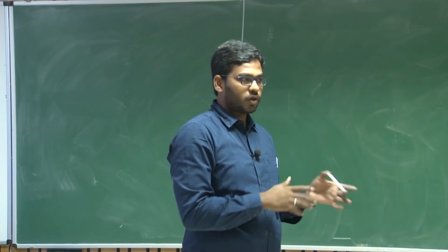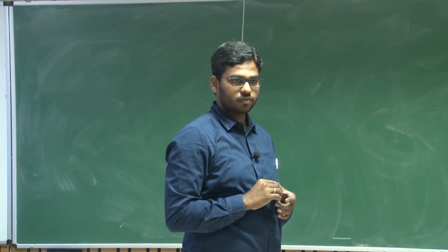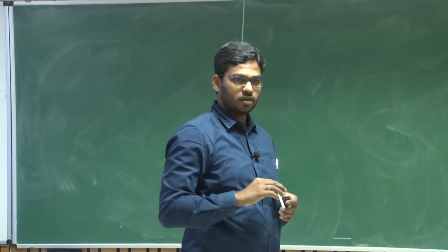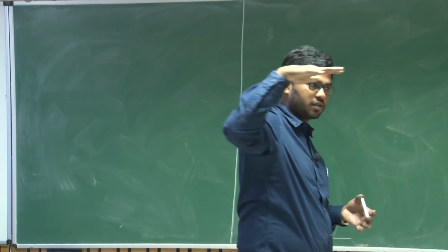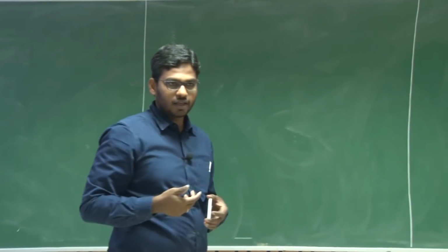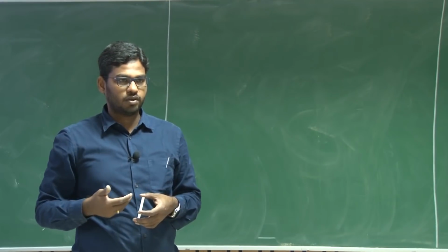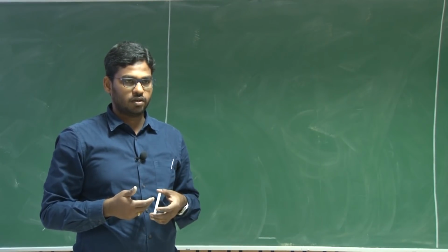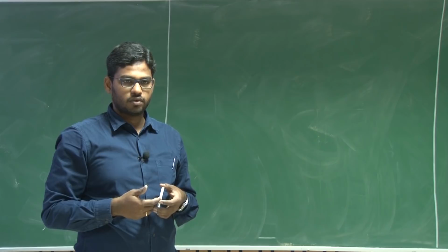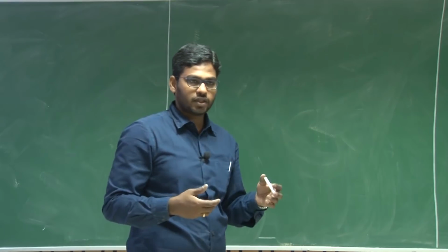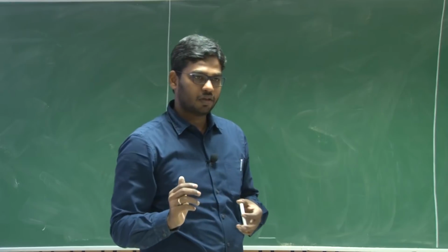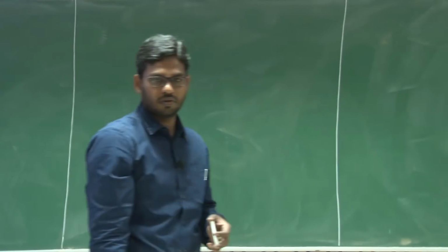So what is the difference between these two? In the first case, we call it a stable flight. In the second case, it is unpredictable, at the same time unstable. It started flipping. And in the other case where the CG is ahead, again it is diving down.